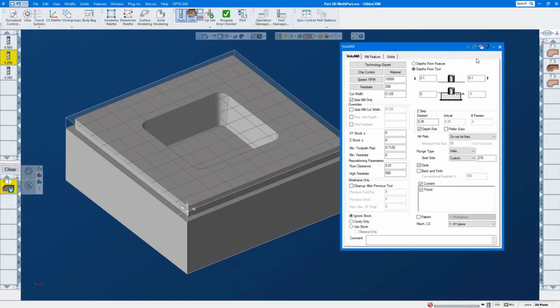So it's still going to helix? No, it will trim out the helix if you pre-drill. So it's aware of the pre-drill. It will choose the point. It'll drop your drill down, and then it will plunge into the hole until it has to helix. So if you have a tapered drill, it'll helix the bottom out. Okay, it's good to know.